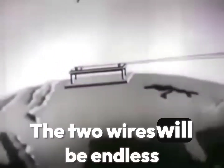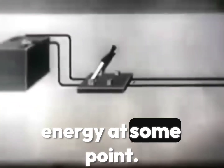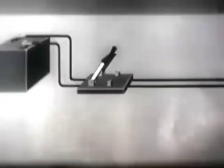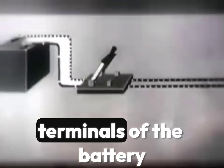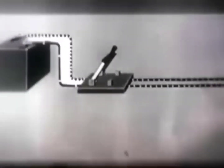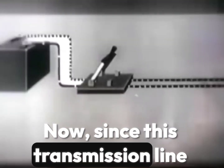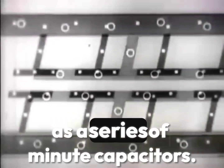The two wires will be endless or infinite in length. Now let's connect a source of electrical energy at some point. Even with our switch open, we know a voltage exists between the terminals of the battery and up to the open switch. Now, since this transmission line consists of two wires insulated from each other, they act in effect as a capacitor, or for that matter, as a series of minute capacitors.